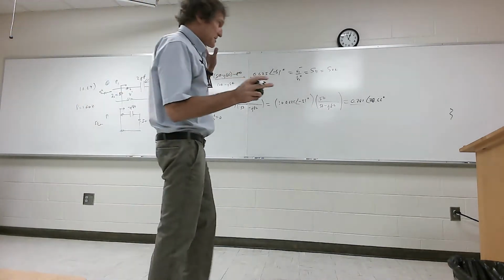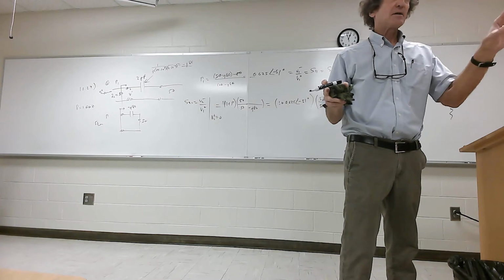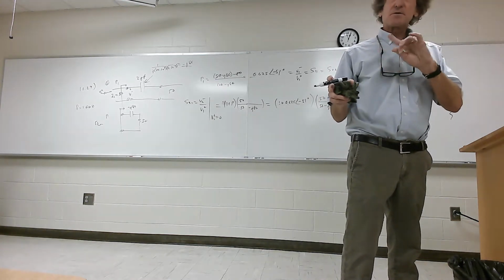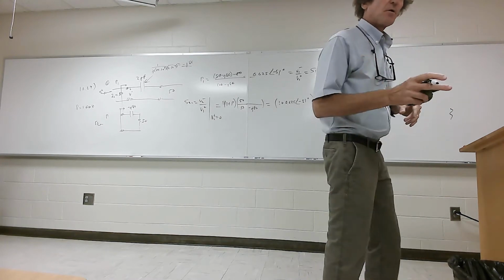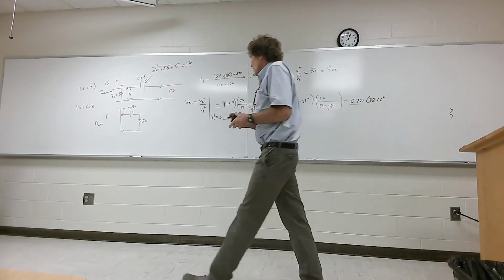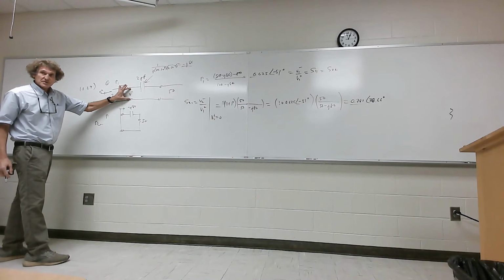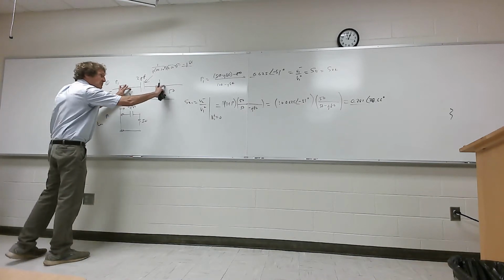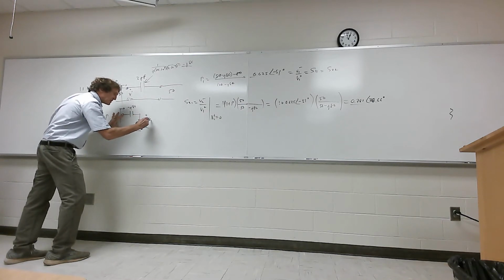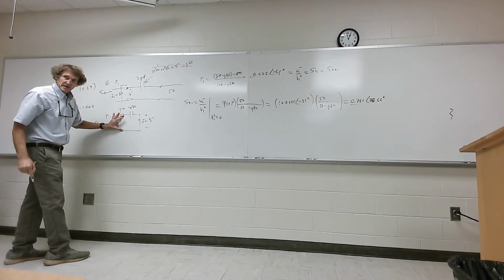I know because you remember the input impedance to waveguides? That calculation drives people nuts a lot of times, and this type of calculation does too. There's a lot of reasons for it. Where did you get the 50 over 50 minus J80 again? All right, think: we've got the transmission coefficient times V1 there. Now I have to find out what V2 minus is. If you look at this, it's simply voltage division. That's V2 minus leaving, so it's going to be 50 over 50 minus J80, voltage division.